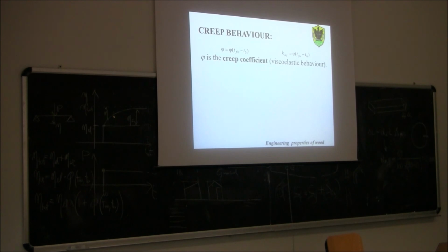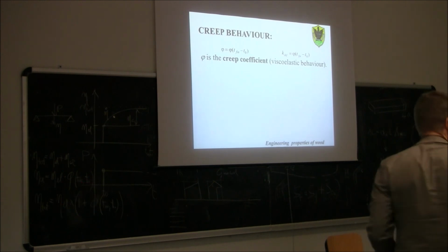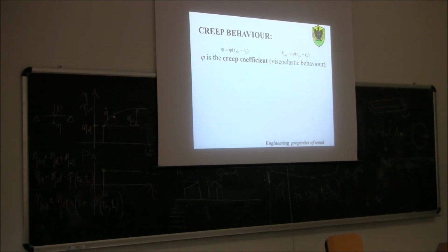φ is the symbol to denote the creep coefficient in concrete structures. For timber we don't use the symbol φ, we use another quantity, only the notation is different, called kdef. So kdef is basically the creep coefficient of timber. The creep coefficient of timber does not depend on both t and t0, it just depends on the difference between t and t0. So it's a function of t final, t infinity, if you want 50 years, minus t0.